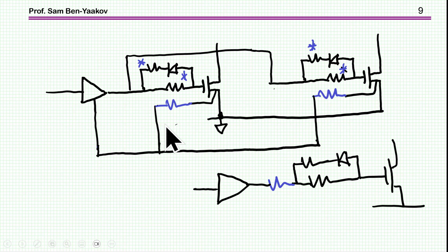Now, when you do this, you increase the resistance of the loop here of the drive to the gate, and I'm showing it here in a more intuitive way. It's like adding your resistance here. So obviously you'll have to compensate for this additional resistance by reducing these resistances here so that the total turn on and turn off resistance would be the one that you would like to have.